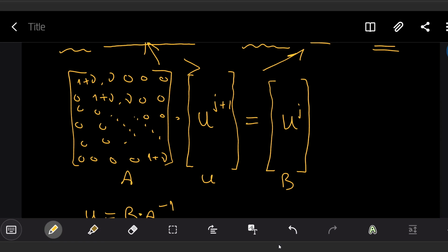You choose a Courant number from the point of view of two things. First of all, you see if your solution is not breaking, if it shows physical results. Not breaking means it is not crashing, and it does not show, for example, negative pressure or strange values of flow properties.